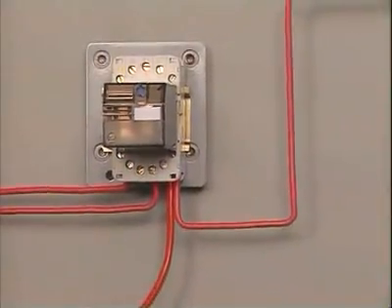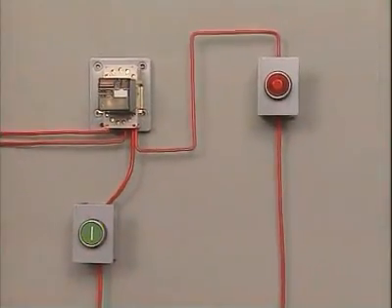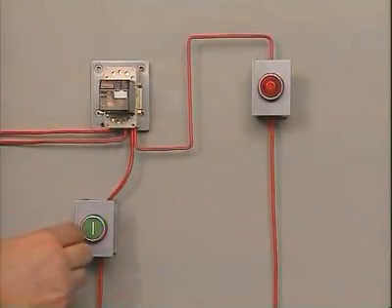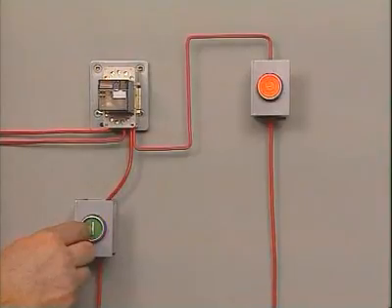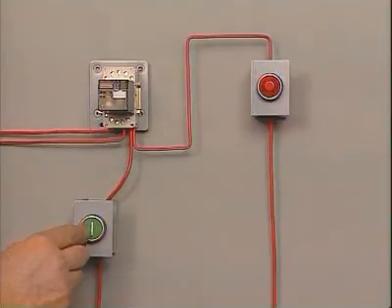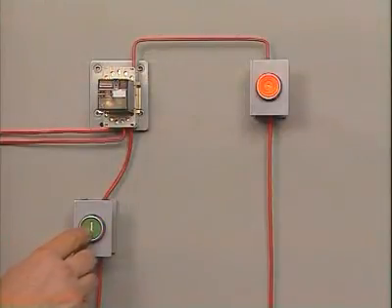The pin assignment of a relay determines the logical function. In the case of a normally open contact, input signal at the coil leads to output signal at the contact. That is logical function identity. In the case of a normally closed contact, input signal at the coil leads to no output signal at the contact. That is negation, or a logical NOT.